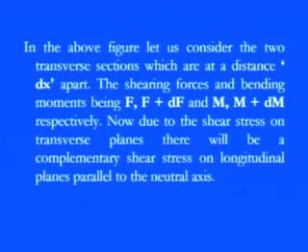Now, due to the shear stresses on the transverse plane, there will always be complementary shear stresses on the longitudinal planes parallel to the neutral axis, just to balance the equation. Otherwise, what will happen because of these shear forces and the bending moment, the sagging moment? We cannot get the exact equilibrium position, and for any analysis this is a must: the equilibrium position must be satisfied, and only then can we apply all those equations.